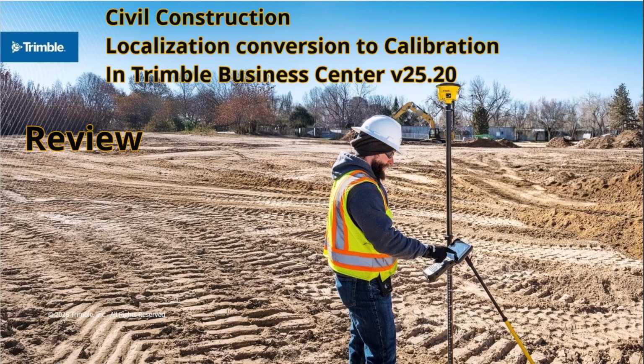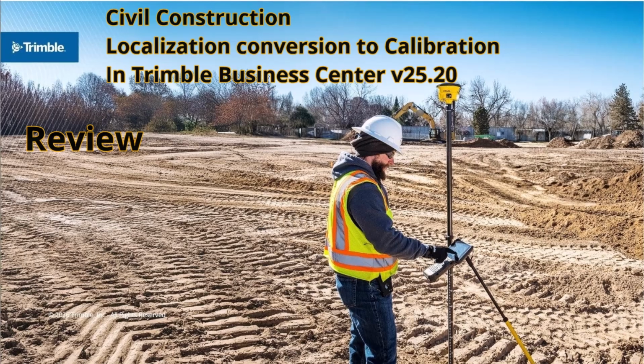In review, in this video we have demonstrated exporting control points from Topcon 3D Office as local control points in a CSV file in the NEZ format. Then we showed how to import control points into Trimble Business Center. Next, we created global control points in Business Center by copying the latitude, longitude, and height from Topcon 3D Office into Business Center's coordinate boxes. Next, we performed a site calibration, matching the global control points with the local control points. Then we exported the DC file and the cal file to be used in Trimble machines and field controllers. This has been converting a Topcon localization file into a Trimble calibration or DC file.